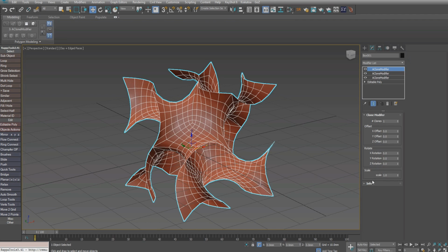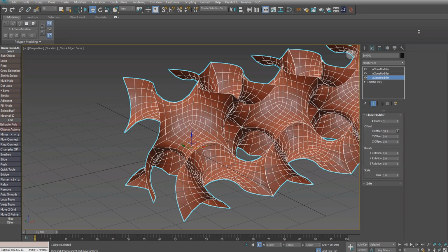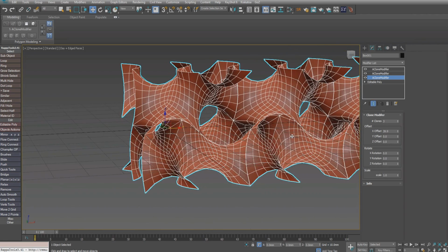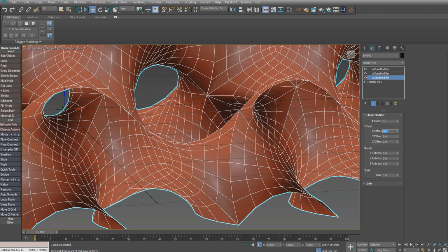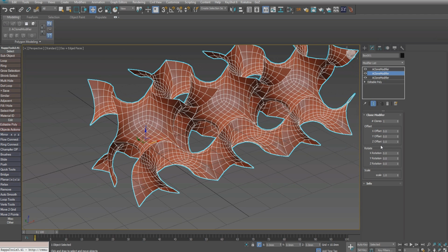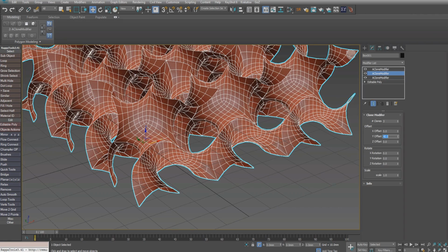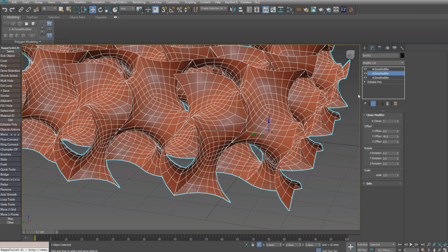I want them to line up perfectly. So I'm going to add, this is 3ds Max 2017, using the MCG modifiers, a clone modifier, 3 of them. And then on the first one on the bottom, I'm going to add 3 clones and just move them out on the X offset. Since this was created to 20 millimeters, I'll just type 40 on there, and that should line up each one perfectly, since each one is double the area of the first one.